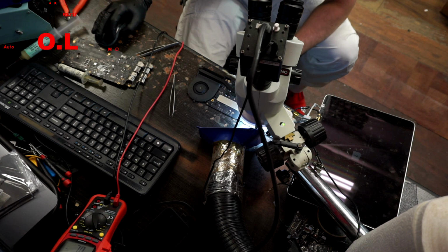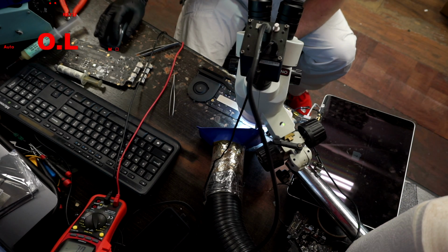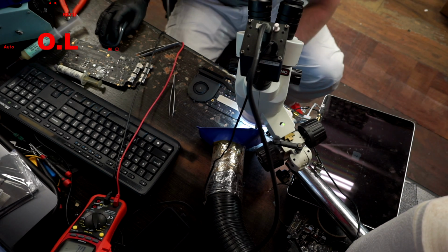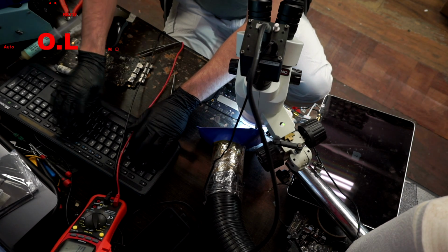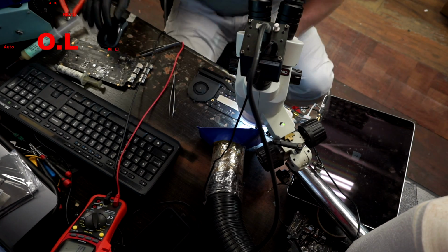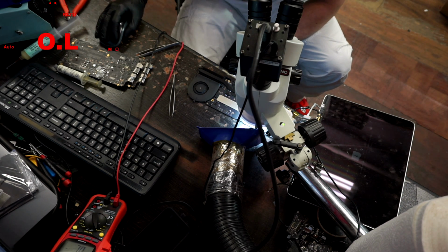That a bad LED driver can make your life a complete living hell, as it just did for the last hour or so for me. As well as the cap. So the cap was probably killing all the LED drivers that I was putting on. So if you short that line to ground, maybe it can kill the LED driver. That's the only thing I can imagine at this point.